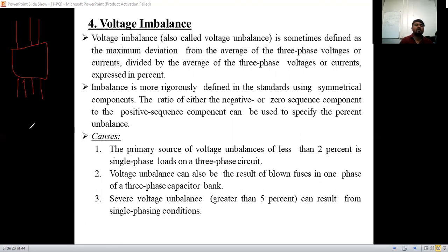Here in one circle we have fixed the transformer, whatever persons are staying here are going to use one phase and neutral. The persons in this area use another phase and one neutral. And the persons in this area use another phase and neutral. Like that, the load is distributed. The 3-phase load is distributed into single phase loads.